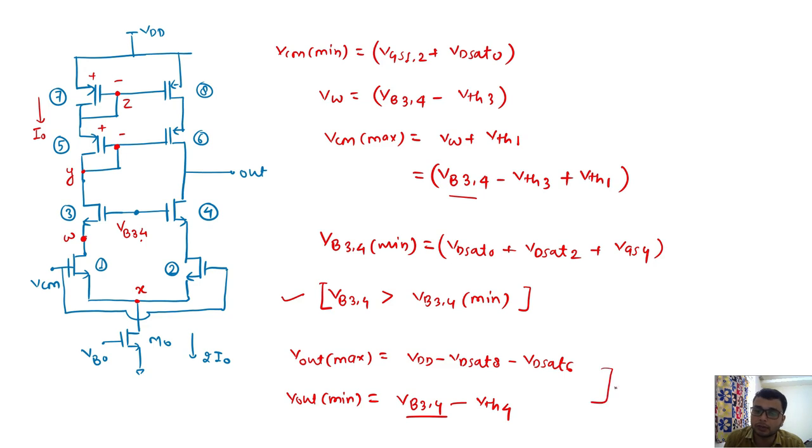So from here we will calculate the output swings, and from this section we will calculate the input swings that we can apply, the maximum. So this is one structure, but here there is a swing limitation problem. I am not telling about this thing, but it is important for the interview. This particular structure that I am using as a load, the PMOS diode connected devices, two back-to-back diode connected devices, are consuming more headroom. So this problem I will discuss in some time.